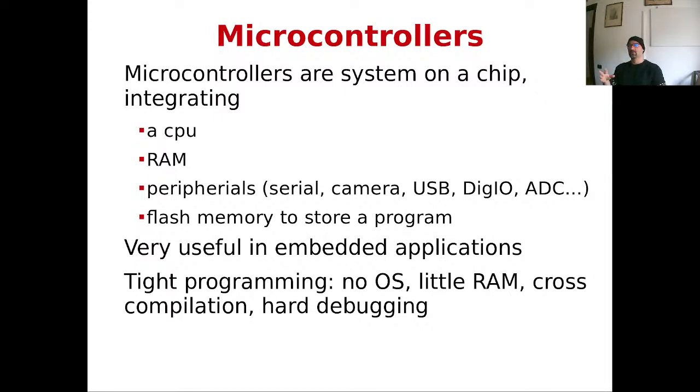You have instead to compile your program on your host machine and then upload it in a certain way on the microcontroller. Plus, debugging is a hell because you don't have a screen attached to the microcontroller, and so you lose the most powerful tool for debugging ever, which is the cout or the printf, in case we're talking about C programs. However, there are ways to debug these applications with special debuggers that get connected to the chip. They slow it down, and then they allow you to see step by step what's going on with the execution of your program.